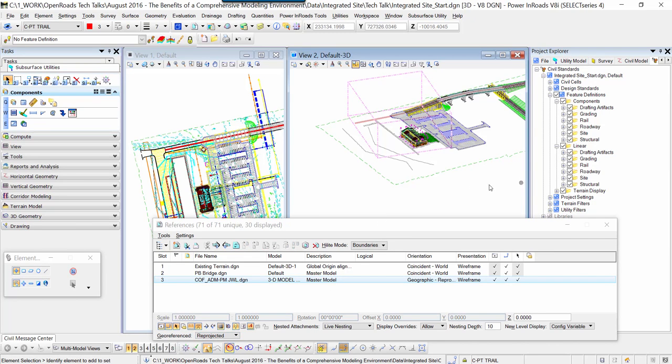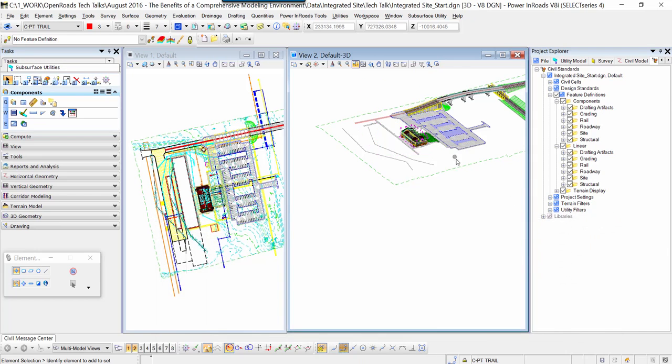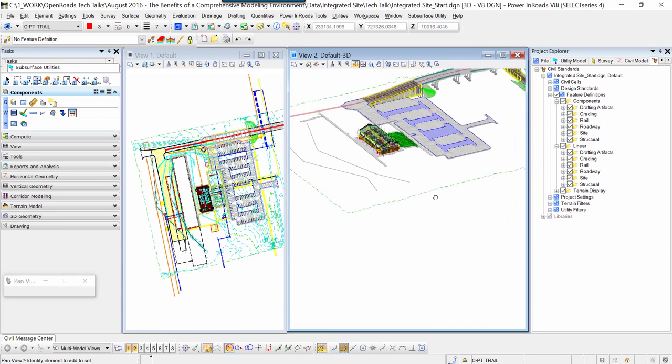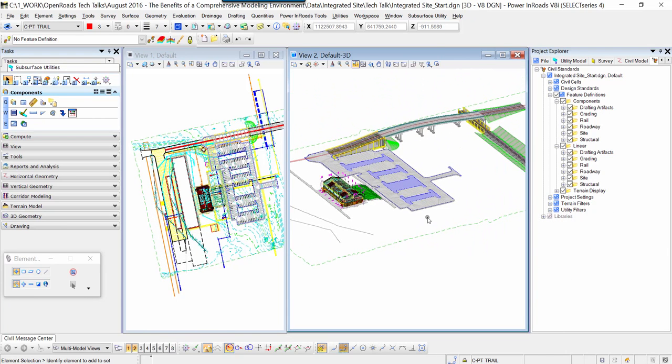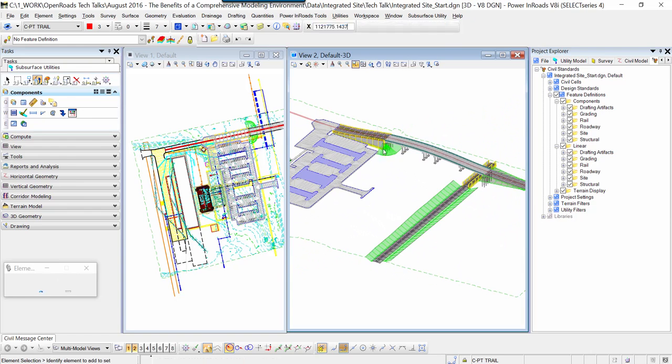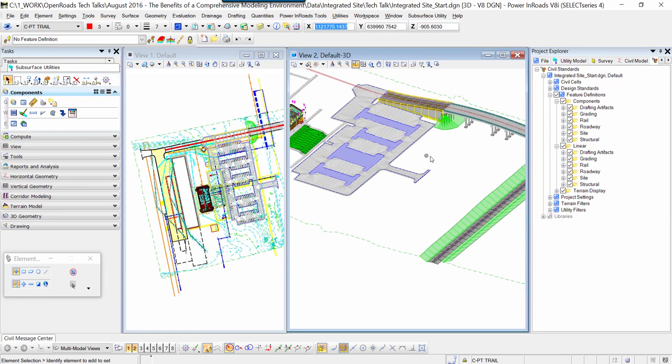An important part when it comes to modeling and compiling data within a comprehensive model is to be able to adjust stuff geospatially. I need your building to reference my state plane coordinate system and so forth, okay? So we've done that. I've referenced it in. We geo-referenced the building in. And so now we can see more of what would be a compilation of our engineering model, okay?